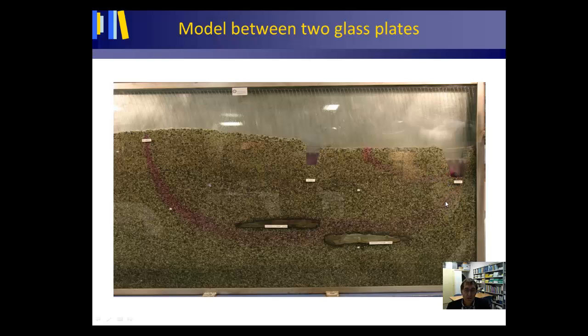So what do we see? We see that water is flowing along curved pathways, and we see that water can easily flow upward from a low to a high elevation. There's no problem in that. And also in reality, rivers are fed from below. And here we see, if we look here, we have a larger column of water than if we look there, we have a shorter column of water. So water is flowing from a lower water pressure to a higher water pressure. It's flowing from a high to a low elevation, but from a lower to a higher water pressure.